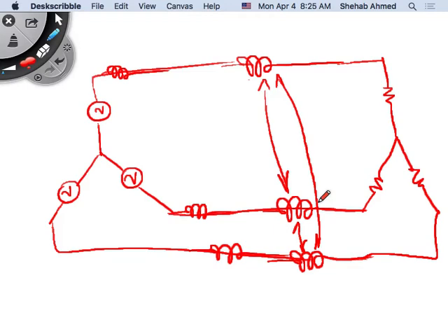So for a very long line, there's the transmission line effect, something called the reflected wave effect. If you have lightning, for example, striking a certain point on the line, the transmission line model may amplify the lightning waveform by the time it gets to the next tower.